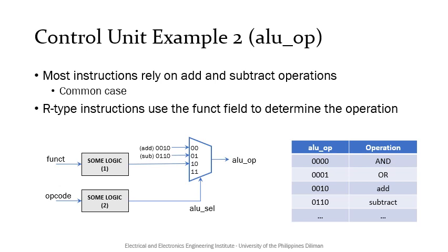We then must design the logic block for the opcode to output an ALU select signal equal to 10 when the opcode is 000000, as is the case for add, subtract, and or instructions.